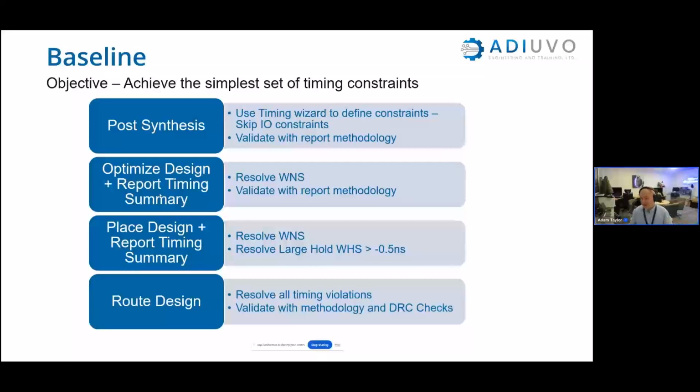Now, this is an estimate at this point, but it's going to give us some worst case negative slack that we can go away and investigate and try to get to the bottom of. Once we're happy that we've addressed any issues that come up from this optimization stage, and it's going to be an iterative approach, we're going to make changes and changes as we go through, running the synthesis and then the optimize. But hopefully it won't be that iterative, as I'll show you in a minute.